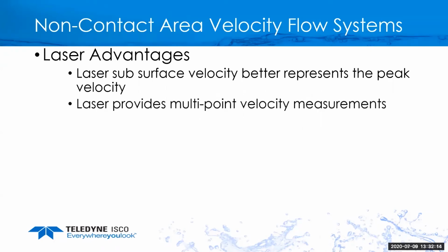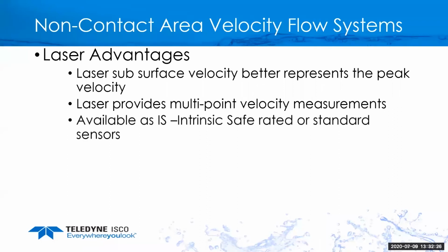It is the only unit out there that will measure a multi-point velocity measurement. So instead of just shooting a shotgun blast at the surface, we're actually going below it and getting very, very precise readings all the way through that water to a point. It is available as an intrinsic safe or a standard. So now you can take the worry out of your hazardous location.